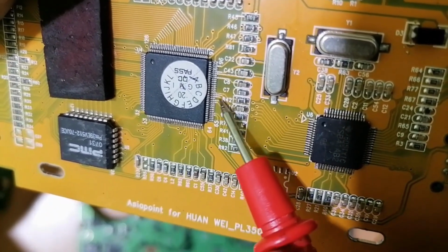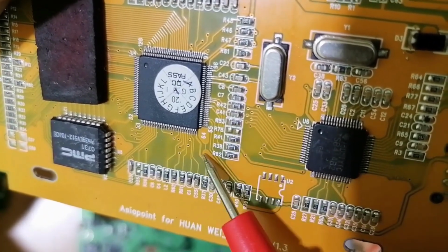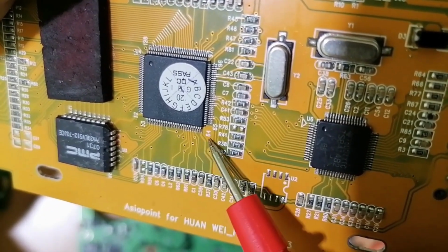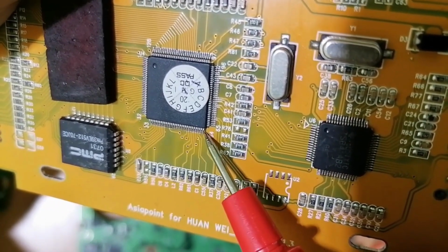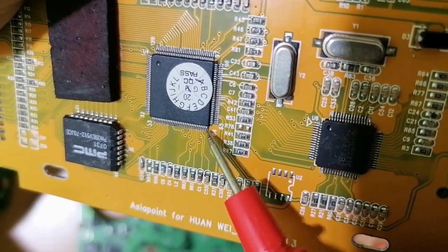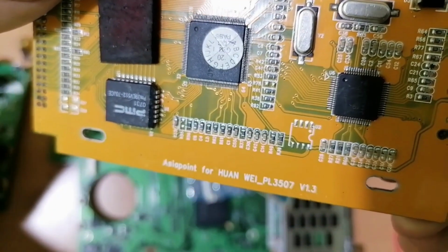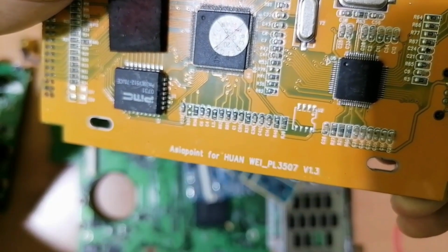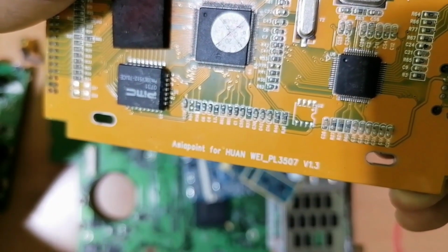Those also. And over here also we have control signals. But this bolded line here means this pin, the pin 64, holds VCC. So using this method, you can now find the input voltage for every IC without the schematic.